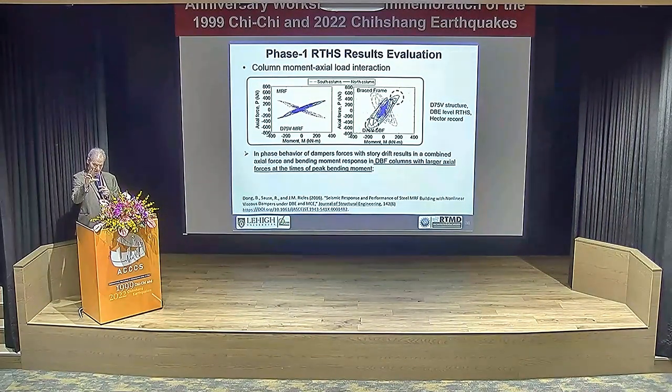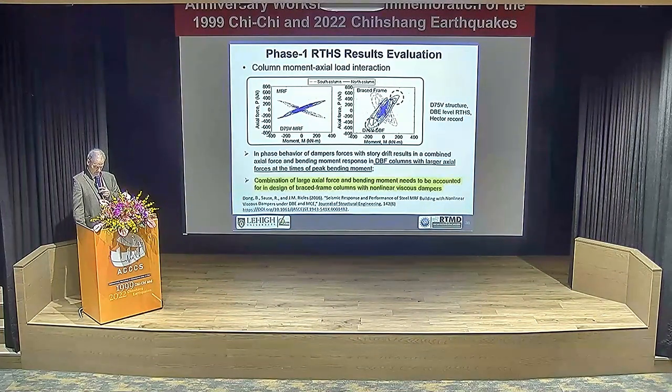You just throw the dampers in there. You need to account for the fact you may increase the axial force significantly, and the columns could fail in compression there. So this phasing is very important. And so it needs to be accounted for really in the design. And this is documented in some of these papers here.